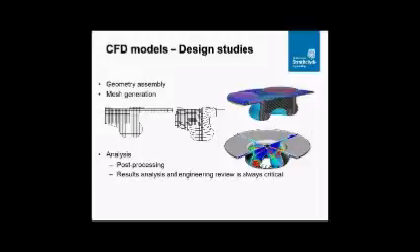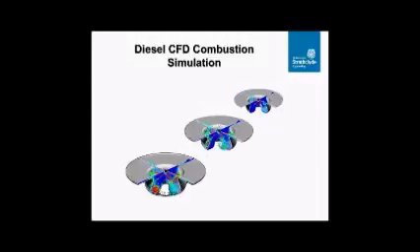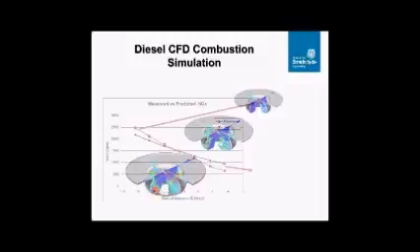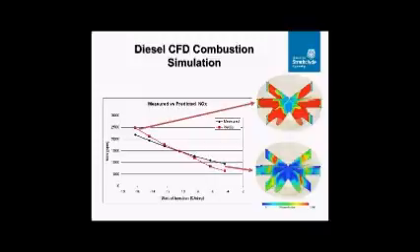Here again, we have a three-dimensional simulation. It uses CFD for the combustion simulation. We can see all the phases of the combustion. We can even see the particles of the injection of the fuel. And in this case study, we have measured the nitrogen oxide emissions. We can see that the measured ones with the black line have adequate accuracy compared with the prediction of the simulation, which are the ones with the red line.